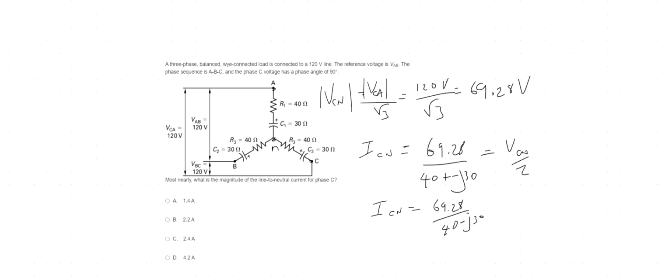What happened when you put it in there? It just spits out 40 minus 30i. Yeah, but now you gotta convert it on the calculator. Put a bracket around the 40 minus 30 and convert it to the phasor form. There's a section to say phasor, right? You gotta practice that again, right?